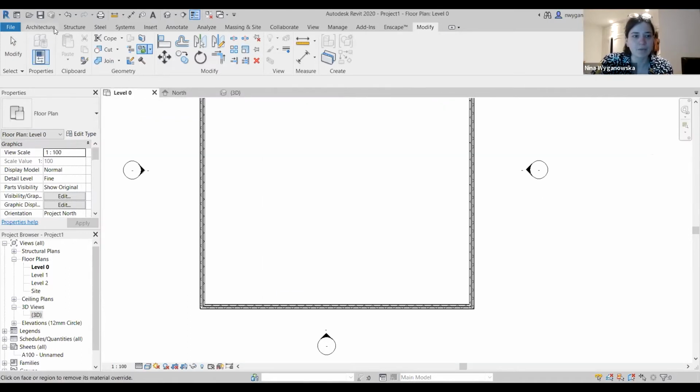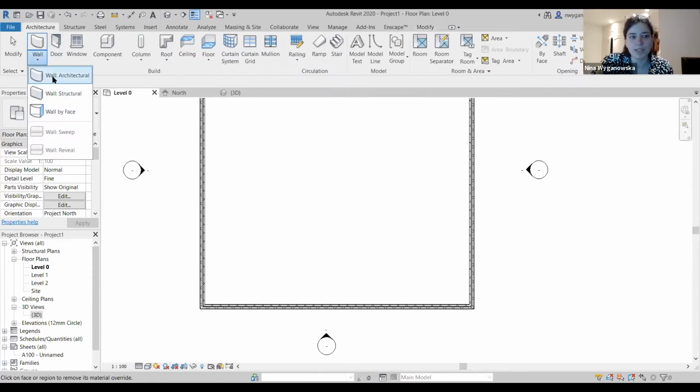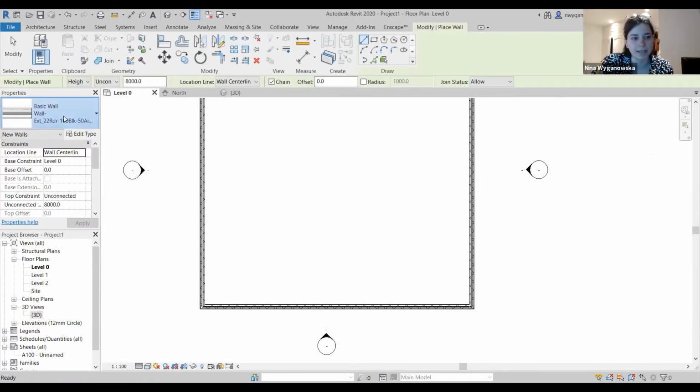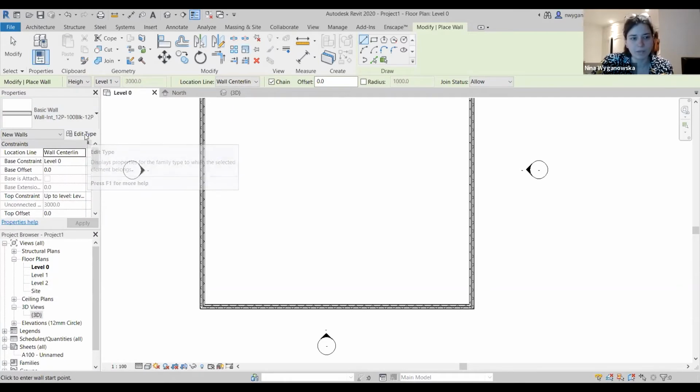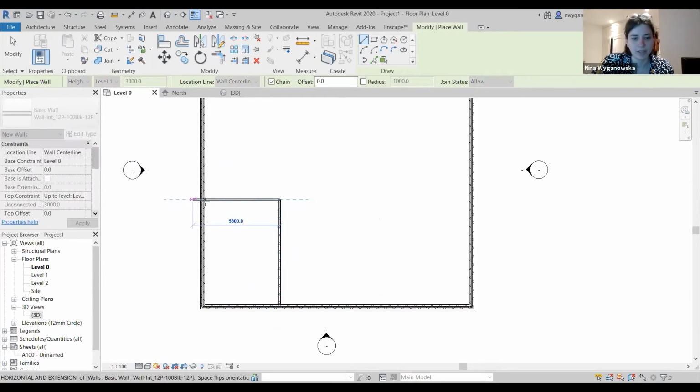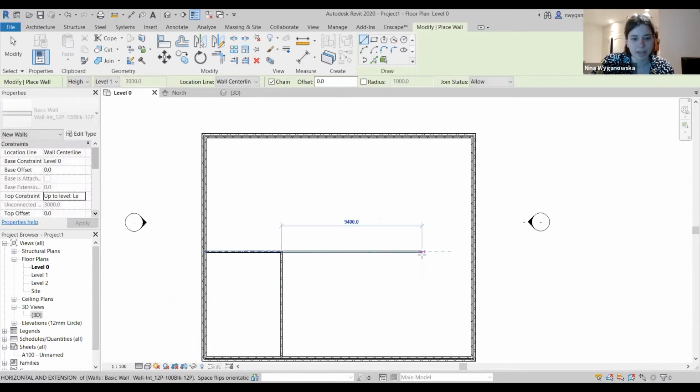And let's say we want to add some rooms inside. So we're going to look for internal walls that have a plasterboard, then block work, then plasterboard again. So it's quite a thick wall. And just before I do that, it's set up to level 1. And let's just set it out to be big rooms in the house or whatever. You can adjust the sizes of the rooms as well.